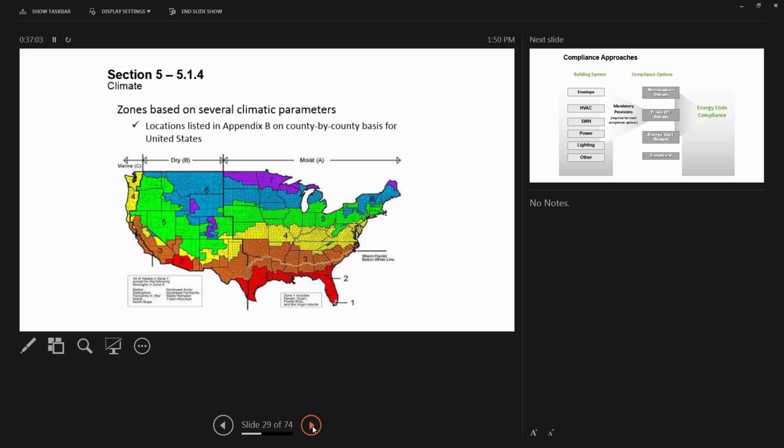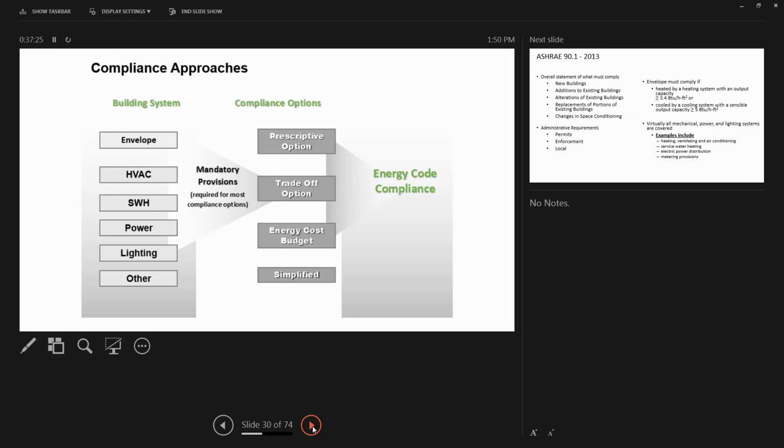All of these standards, both the codes and the ASHRAE standards, and all the programs we're going to touch on here after a bit, are all based on climate zone. Because obviously, one part of the country is going to have significantly different requirements when it comes to thermal envelope and U values of the windows and moisture control than the other. We'll spend a bunch of time talking about that, but I've got an entire semester-long class on moisture migration and vapor drive, so I don't want to go down that wormhole right now.